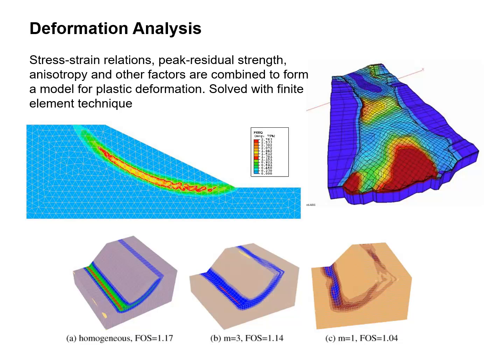Then, based on the weights and the pore pressures and the stresses involved, it looks at the stress-strain relationships along certain areas where the shear stress is high, as shown in some of these figures, and then it comes up with a factor of safety against failure. And so this is what you do when the stakes are high and you need to do a really sophisticated analysis.